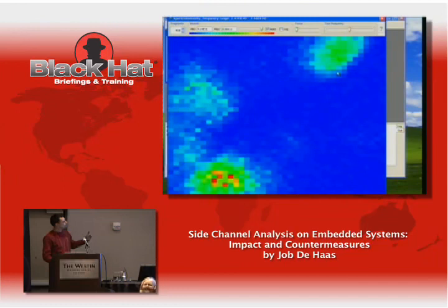And, well, to figure out what this means, you actually need the pictures that Kristanovsky was showing this morning. You need a mapping of the physical chip compared to the signal picture, and then start to analyze if what's coming off like the crypto core on the chip correlates to some signal in the spectrum that is stronger, for instance, and that may be a free running clock of the crypto part that allows you to zoom in to the correct place.